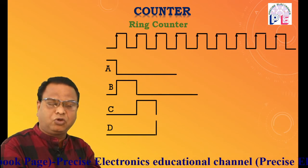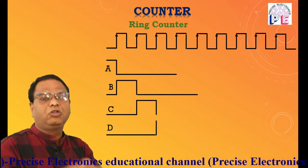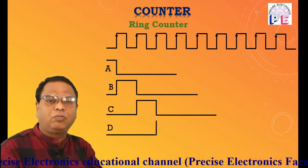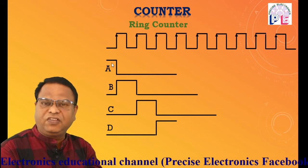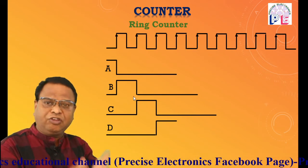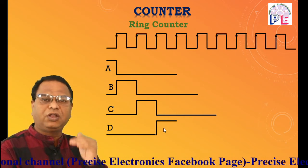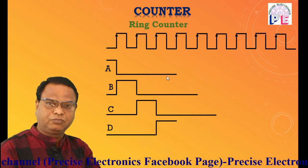C is now in set mode. So the output of C is connected to the input terminal of the D flip-flop, due to which the output of the D flip-flop becomes high. D flip-flop is in set mode. So at the end of the third clock pulse, at the positive edge of the third clock pulse, the output of the counter is DCBA equal to 1, 0, 0, 0.